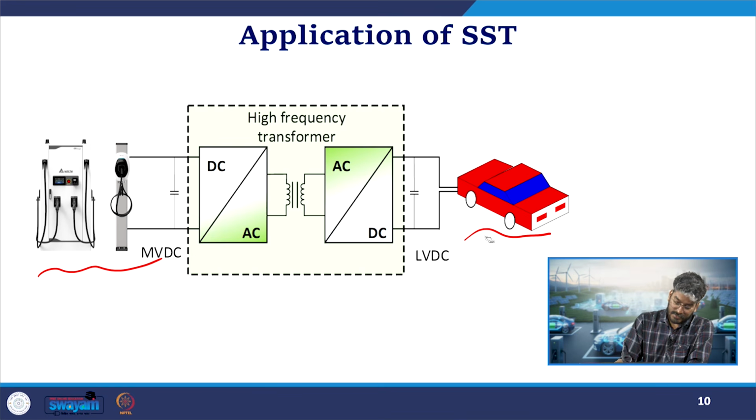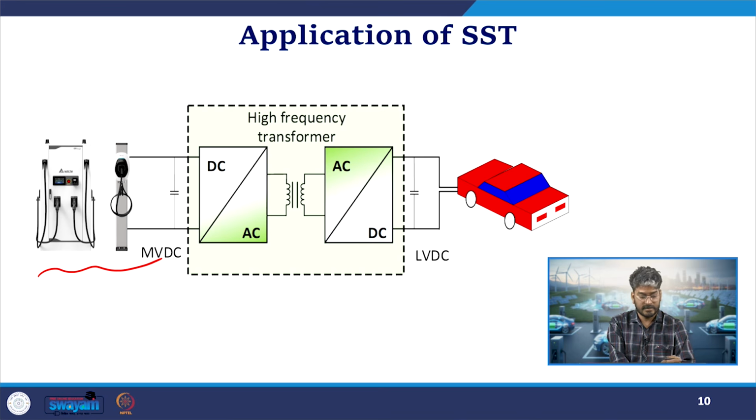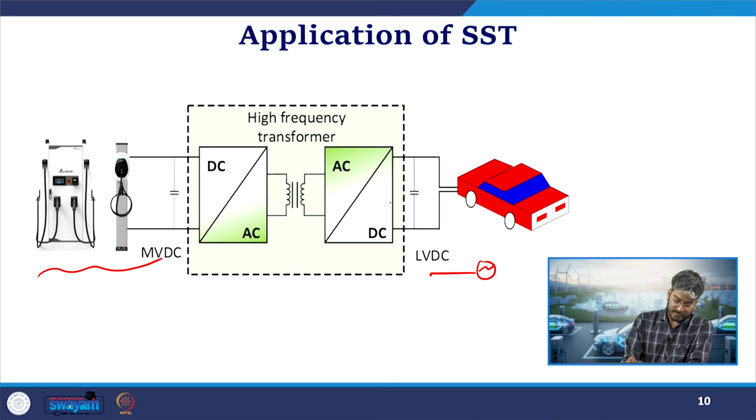Similarly, when I select the MVDC bus for connecting some fast charger, suppose I am developing a charging station which will be connecting multiple charging ports, or which will have DC fast charging facilities, there I will be going for medium voltage systems where it can be 1500 V or more than that. So, for those types of applications, I will be selecting the DC bus. I can have a low frequency conventional grid fed from the low voltage side. Then the AC to DC conversion, then the DC to AC conversion, then high frequency, then our medium voltage DC bus will be the end of our conversion stage.